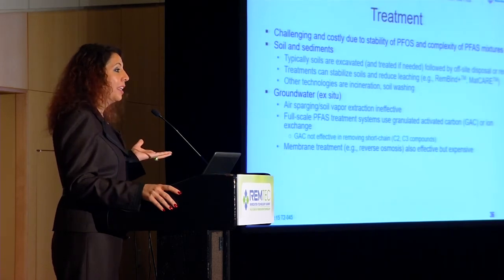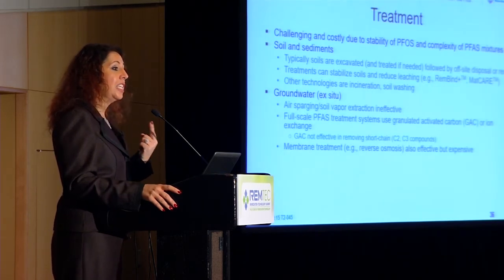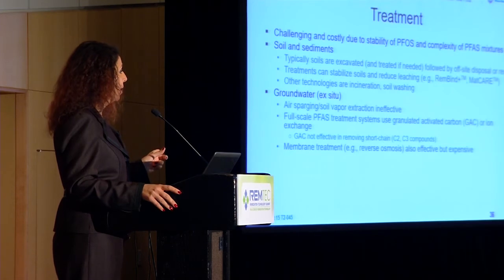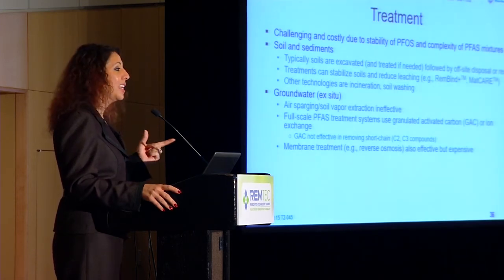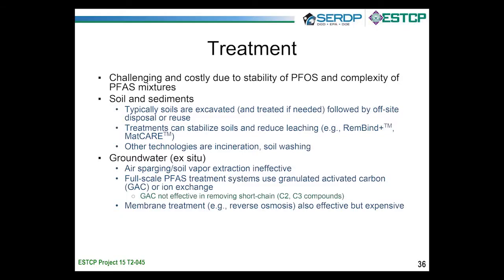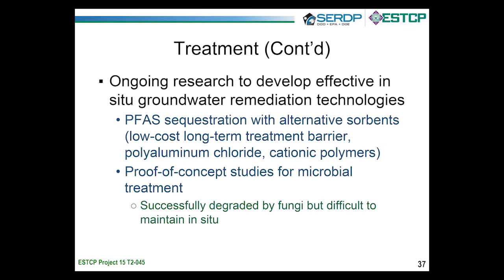One caveat with GAC is that we're designing these systems to remove the C8 compounds of interest. So PFOS and PFOA are the target compounds. So we're not designing these systems to remove other PFASs that are migrating in groundwater that are shorter chain compounds. Membrane treatment is also very promising, but it is more expensive.